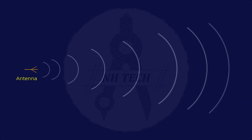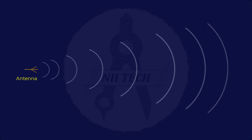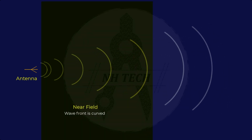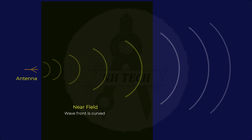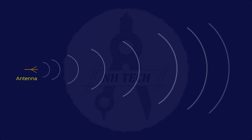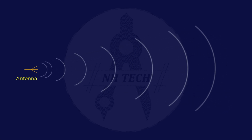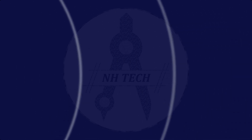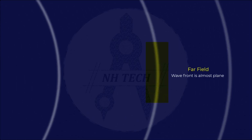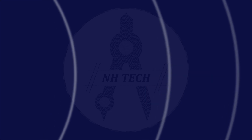When an antenna radiates energy, the electromagnetic wave initially spreads outward as a spherical wavefront. Close to the antenna, these wavefronts are strongly curved, and this region is called the near field. As the wave travels farther away, its radius becomes larger and larger, causing the curvature to gradually decrease. Eventually, over a relatively small area, the wavefront appears almost perfectly flat. At this point, it can be approximated as a plane wave, and this region is called the far field.